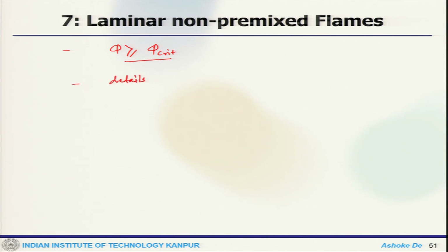There are details available regarding soot formation. It happens because of the conversion of hydrocarbon fuel, with molecules containing a few carbon atoms, into carbonaceous agglomerates containing some millions of carbon atoms in a few milliseconds.